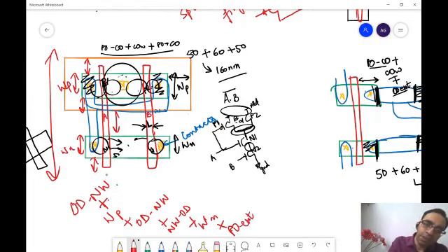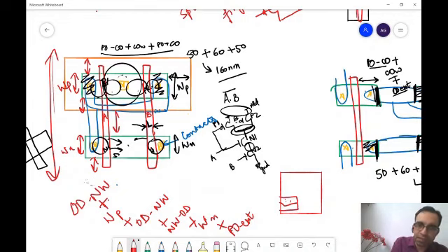And then if I have to consider that I have to make walls, then this cell would come above another cell. Are you able to see this? This whole NAND gate is one cell. There would be another cell that would come beneath it. So I have to ensure this poly to poly spacing is also taken care of.